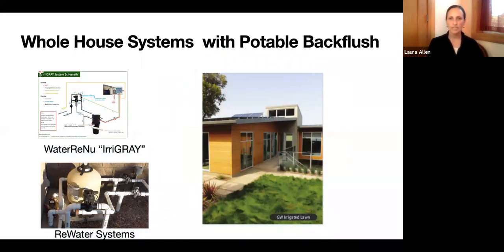There are more sophisticated kinds, like I mentioned early on, that could do a lawn, like in this image. It's not your standard lawn, but it is greywater irrigated lawn, large area with drip irrigation. These systems have a filter that automatically cleans itself every so often, and then you only have to do something once a year versus a manually cleaned filter where you have to clean it out every couple of months. So there's a few out there, and yeah, they cost more.